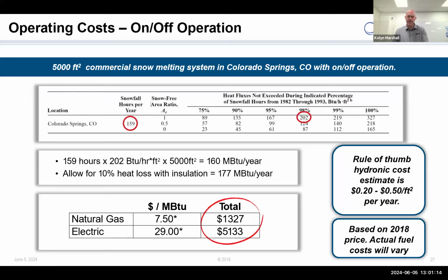And the difference is the serpentine pattern loses temperature linearly along the length, right? So across the surface, let's say that the starting temp is 140 and the ending temp is 110. So I get a gradient across the surface of my snowmelt until the entire mass comes up to temperature. The double serpentine is almost even.